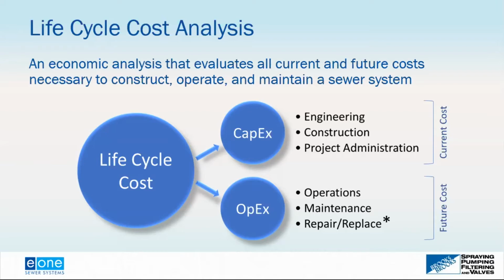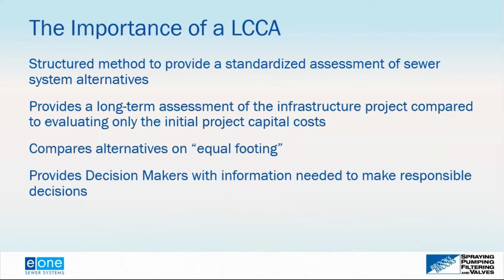Now, when I do life cycle cost analysis, I like to look at replacement cost as an annual cost. Instead of saying I'm going to spend X dollars in 20 years to replace a lift station, I say I'm going to spend X dollars every year and put that into a replacement fund. So when year 20 comes, I have the money available to do the replacement. It just makes the evaluation a little bit easier to take that number and figure out the time frame in which you're going to do that replacement, as opposed to trying to guess when you might have to do that for different components.